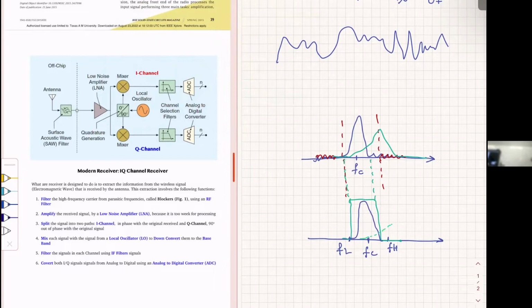So practically, the filters are good for two reasons. They remove all of the noise that is out of your main band because you don't want to have to deal with this. The receiver is a non-linear device. What does non-linear mean? It means that if you take a signal at a given frequency and you pass it through, you will have byproducts of other frequencies. That's what nonlinearity creates. And you don't want the noise outside to create byproducts that come into my band. All right, so I'm gonna leave that.